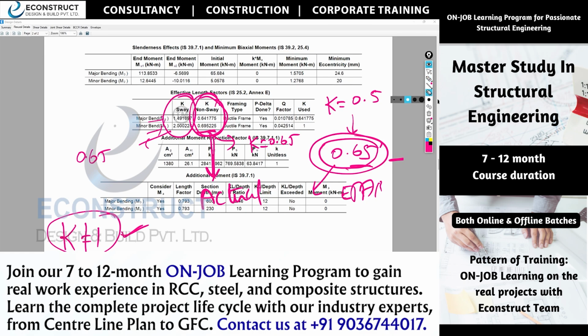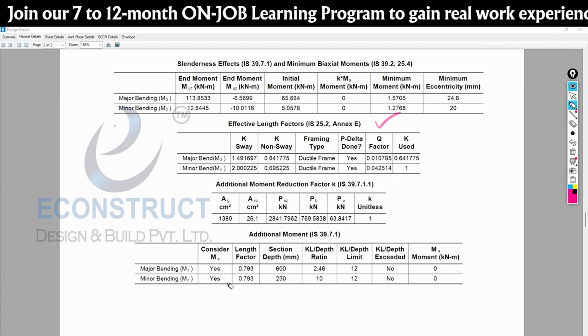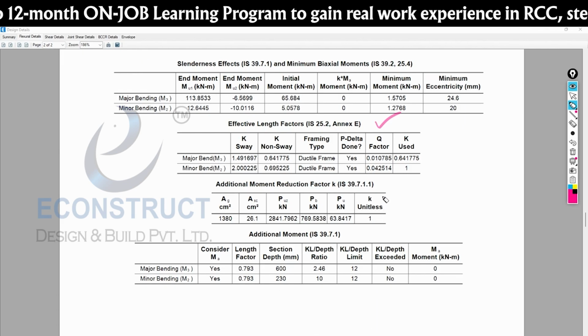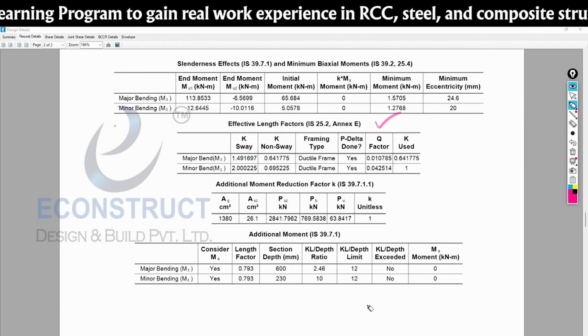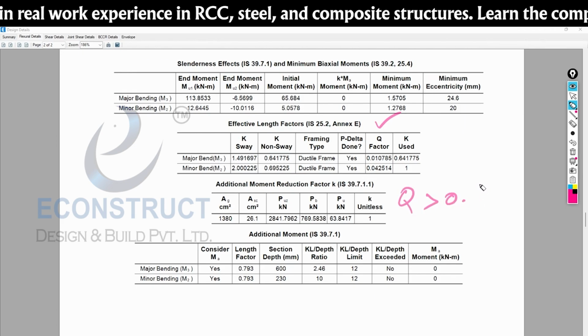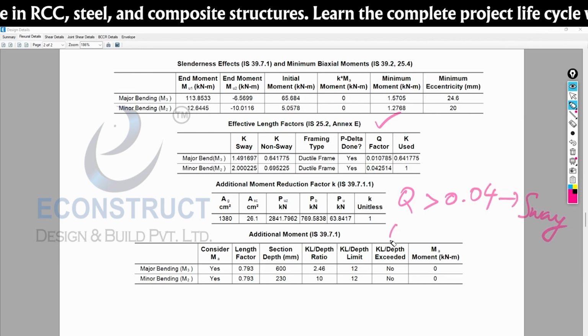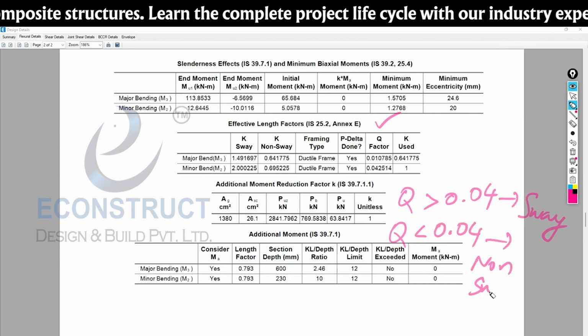Okay, fine. Now how to classify this sway or non-sway based upon your Q factor. So you can see the Q factor here. So how to calculate the Q factor? For calculating Q factor, there is some formula. I will show you in the last. But generally, what is the main condition? If this Q value is greater than 0.04, then that is called sway. And if the Q value is less than 0.04, then it is called non-sway.